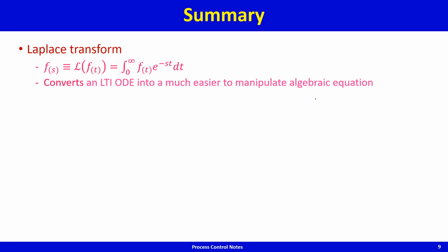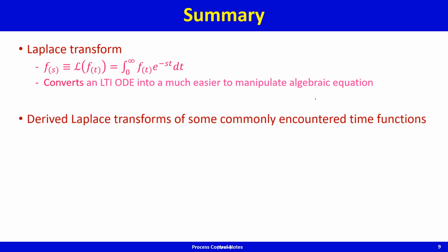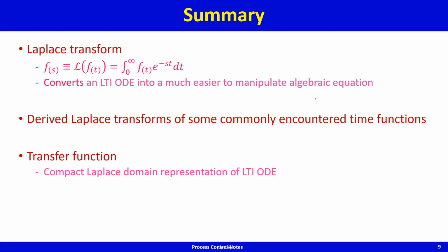With this, let me summarize what we have done in this lecture. We've looked at the Laplace transform, which is defined as shown on your screen. It converts a linear time invariant ordinary differential equation into a much easier to manipulate algebraic equation. We have derived Laplace transforms of some commonly encountered time functions. We've also looked at the transfer function as a very compact Laplace domain representation of the linear time invariant ordinary differential equation. We've looked at some commonly encountered transfer functions. That's what we've done in this lecture.